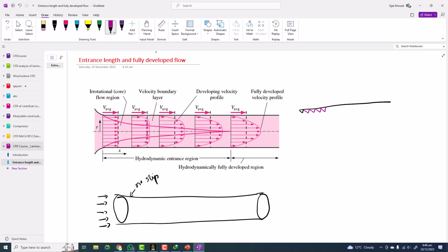You cannot see this with the naked eye, but if you go to the micro level, you will see these small grooves. So what is happening here is that the flow particles will start to stop here. That's known as a no slip condition. And because if you take a look at the surface from a micro level, the surface is not a fine finish, but a rough surface. So that's why the flow will start to stick there, and you will see that velocity will be reducing.